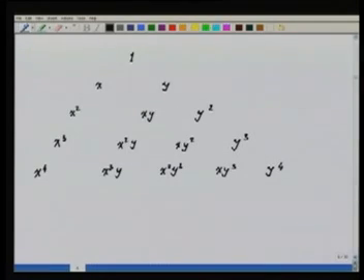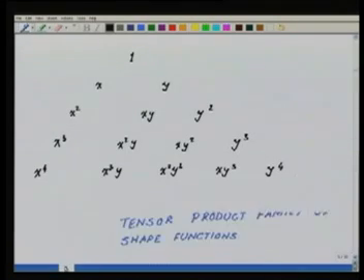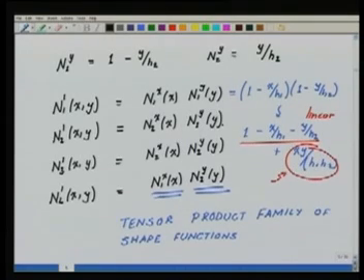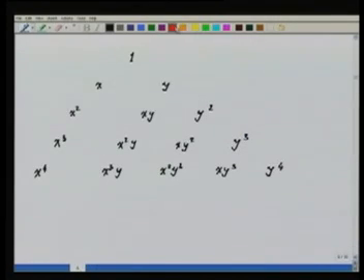So if I expand all of these functions n1, n2, n3, n4, I will find the same feature: they will contain the linear part, that is in terms of 1, x and y, plus they will also contain the product of x and y. So if I come to the Pascal triangle, they will not only represent the linear, they will also contain the xy part. That is more than what was really required to define the linear polynomials.